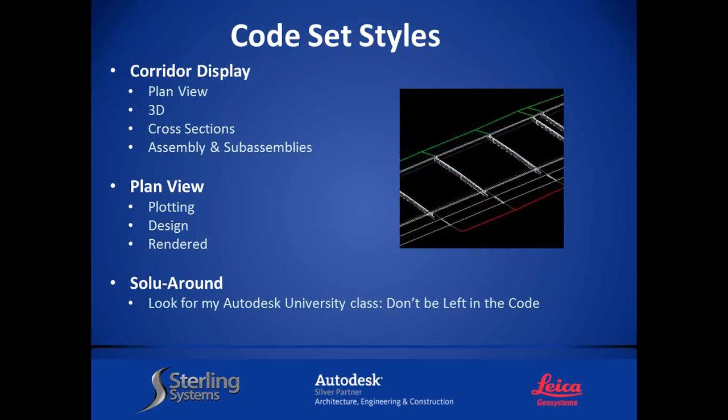You can take this in 3D and orient it in your object viewer, and your information will show up in that 3D as well. Try not to add what they call shapes to your 3D view, because it will really bog down the system. The less information that you show, the better. Any type of roadway design that you are working on, keep the code set style super simple, and you will get done much quicker on all of your regens, all of your designs, all of your updating. So a very, very big tip.